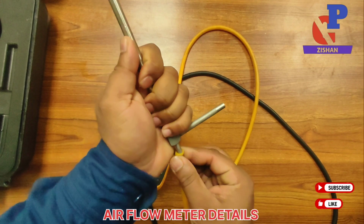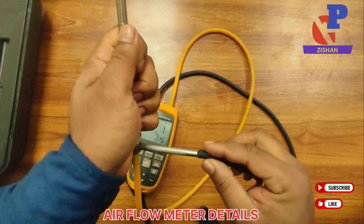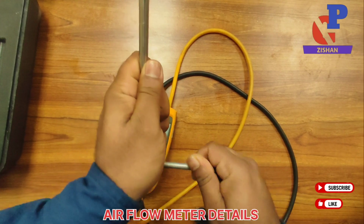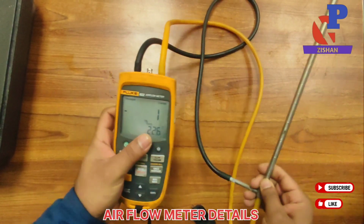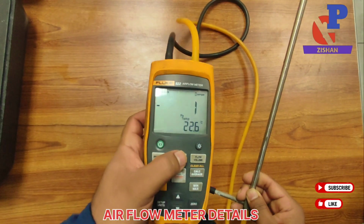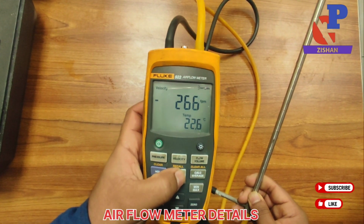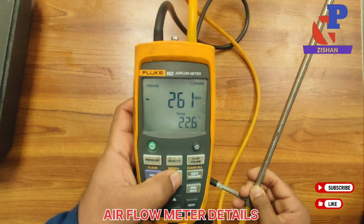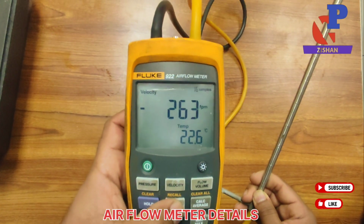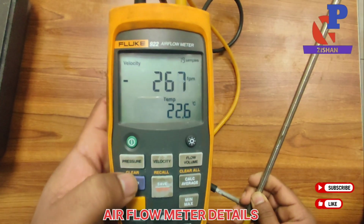For the velocity and flow volume, we have to connect the static pitot tube. From this tube we can take the different velocities and flow volume inside the duct. Suppose we are going to calculate the velocity, we have to connect both hoses, positive and negative, and then take reading samples from inside the duct.